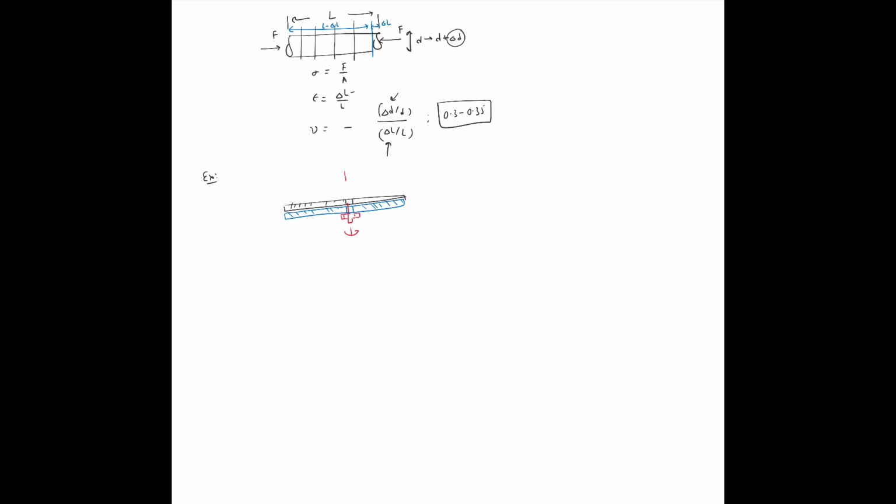So let me bring the bolt down. So we are here, and here is my bolt head now. All right. Now, when I do this, I essentially put my bolt in some sort of tension, right? So if I look at the free body diagram of the bolt alone, what do I have? So free body diagram of the bolt. I'll draw it a little bit bigger. So here's my bolt. And because I've tightened my nut, the bolt is in tension with some force T.